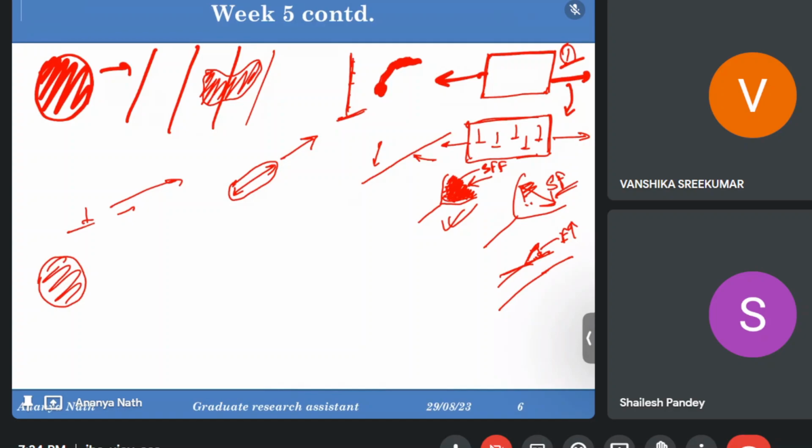So we are just heating up the material to a certain point below the melting point, but above the recrystallization temperature. We are holding the material for that particular time, which is the recrystallization time, and then we are cooling it down. This is what annealing does, and this is how we get some strain-free new grains. So what does this strain-free new grains mean? Anyone? This line was repeatedly mentioned in the last two lectures, lecture 4 and lecture 5. Some strain-free new grains are born.